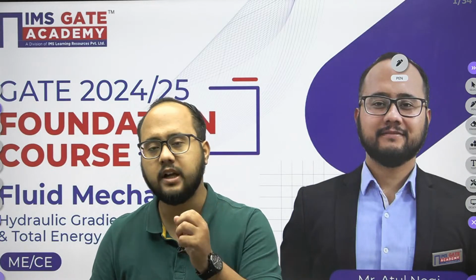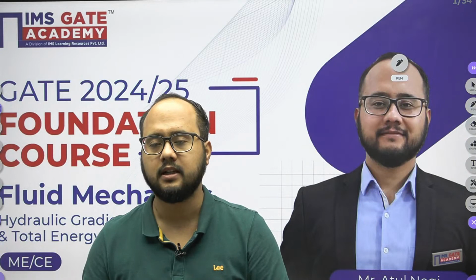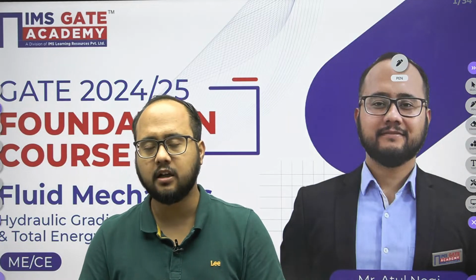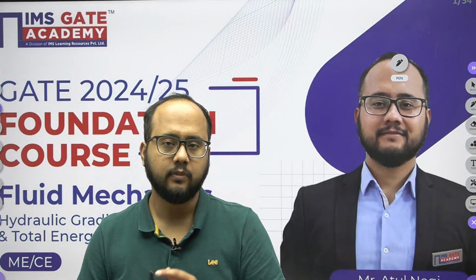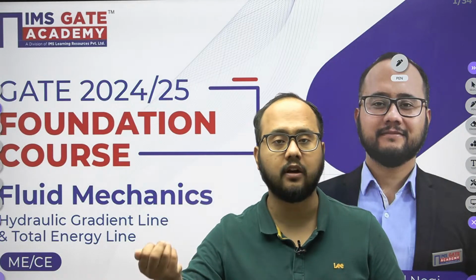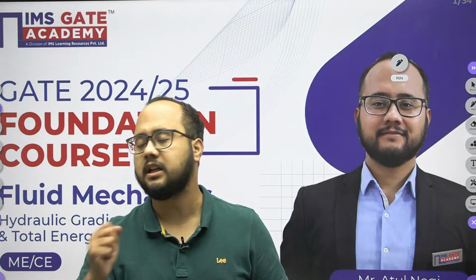First of all we discussed the major losses and then the minor losses, and I hope you remember all the concepts related to that. Major loss is because of friction, because of frictional resistance. And the minor losses are because of the change in velocity. Either the magnitude of velocity can be changed or the direction of velocity can be changed.